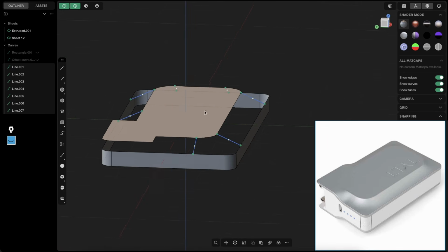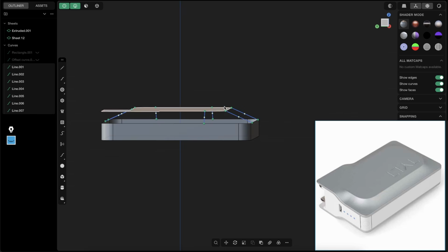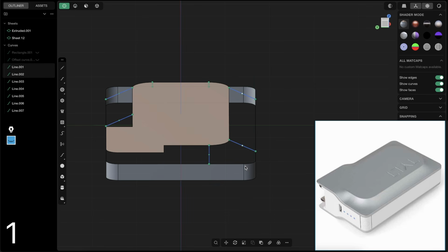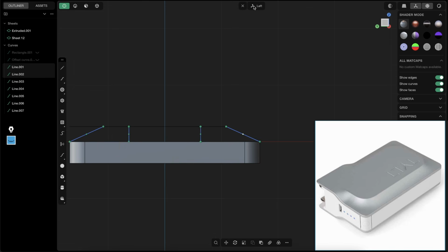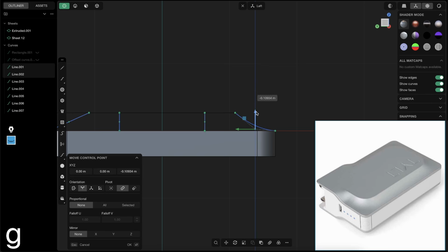And now, there are a few different ways, but just for demonstration, something very simple. Let's press 1 and select just those two which are on the same edge, go to the left view or something, so you see from the side, and press G. And now, very important, Control click and snap to this edge. Why?